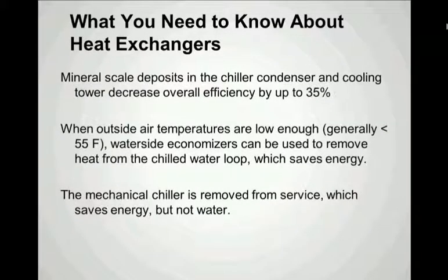So what do we need to know about heat exchangers? First of all, keep everything clean. For good heat transfer, these mineral scale deposits that can form in the condenser and cooling tower can rob you of efficiency by up to 35%.